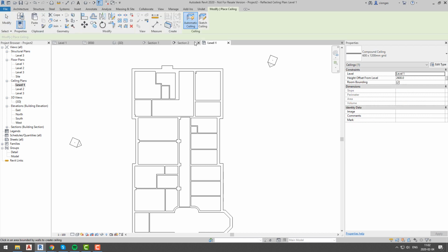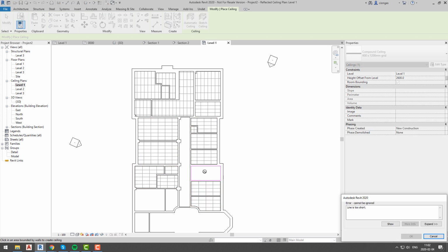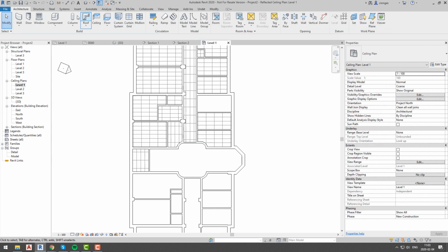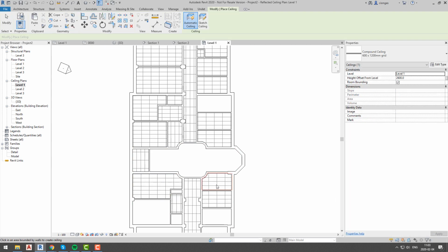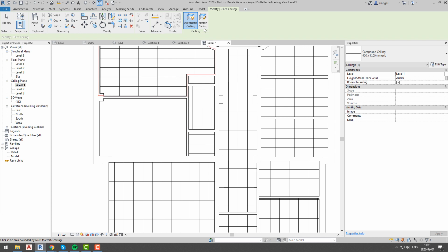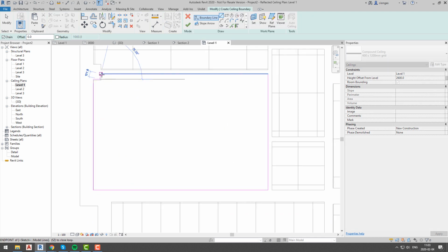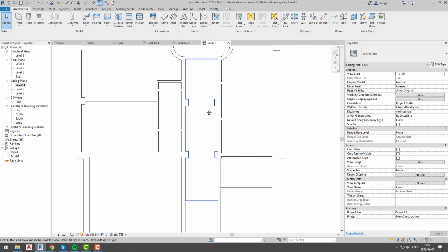We will hide those sections in this view, so that we can clearly see boundaries of each room. We will go to Architecture tab and we will select Automatic Ceilings and add them to each room. If Automatic Ceiling function will not work, we will use Sketch Ceiling instead. Once we have our ceilings, we will go to each section view and we will adjust ceiling level.